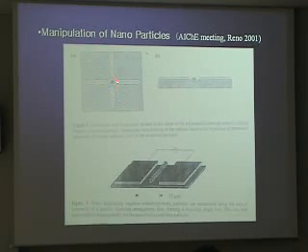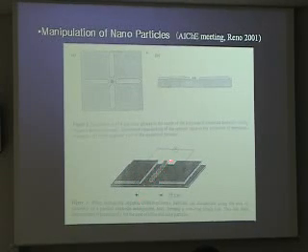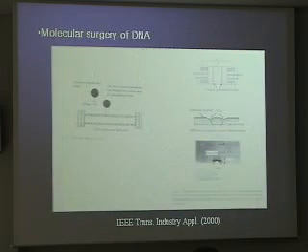So when we have a quadrupole of electrodes, okay, at the center, the electric field is minimal. So particles are collected at the center, okay? And if you have two electrodes like that, then along this line, the electric field is minimum. Here, the strongest point. So we can align, okay, particles. So this one was from the CHE material last year.